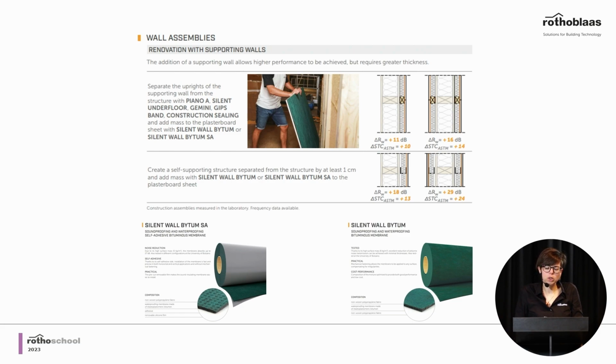Pay attention that all these solutions cannot be doubled. So if you look into the solution that we have proposed, if you are working just on one side, you can see an improvement, for example, of 18 dB. But if you work on both sides, the improvement is not double, it is less than double. And this is due to the fact that acoustic performance works in logarithmic scales, and unfortunately, logarithmic scales work like that. So we cannot simply sum the benefits, and this is what happens.